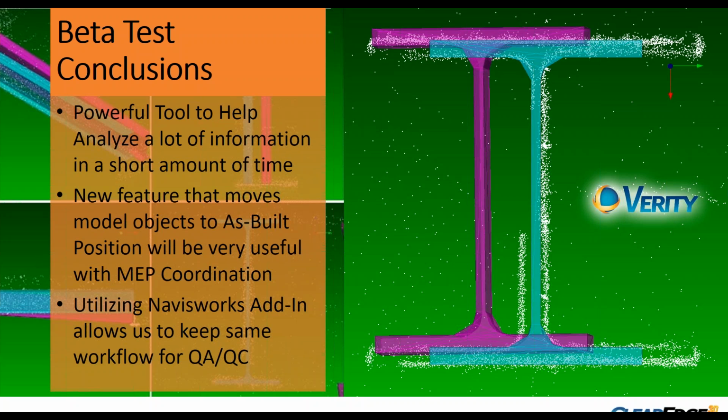Level 2s I tend to do in the middle of the floors where there isn't a lot of close-by data. But the TX8 we're using is a little different, and we haven't sat down and looked at the Faro comparison between the TX8 and the different Faro units. I knew the new Faro that just came out is pretty quick as well. We didn't do color on this one, which allowed us to go a little quicker. The TX8 that I have does not have a camera embedded, but you can use a 360 camera or a fisheye lens with a DSLR, which is what we use.